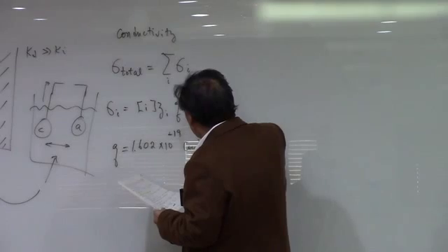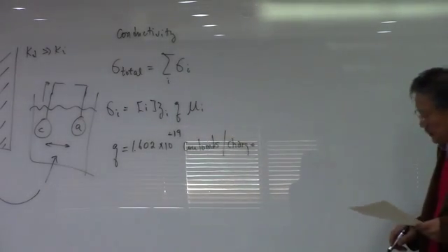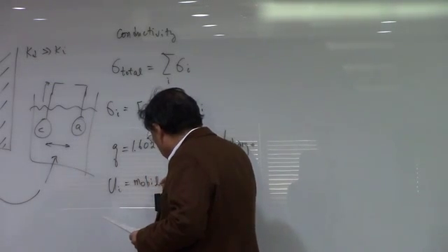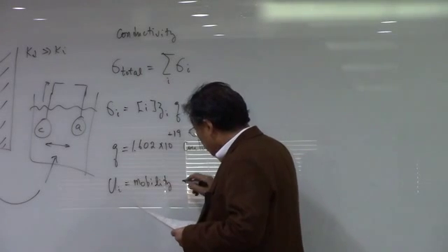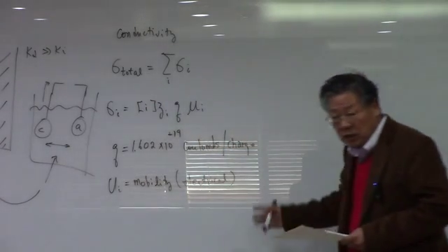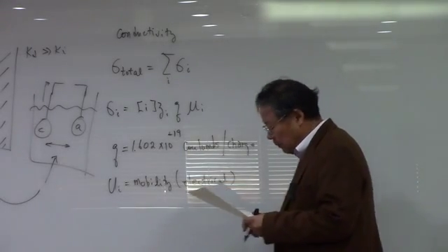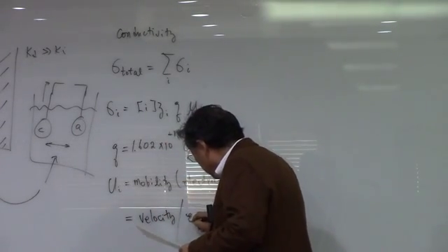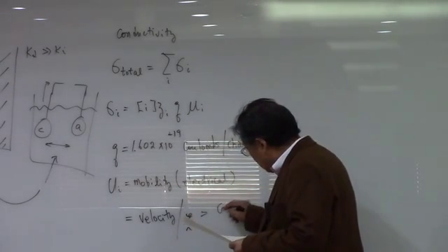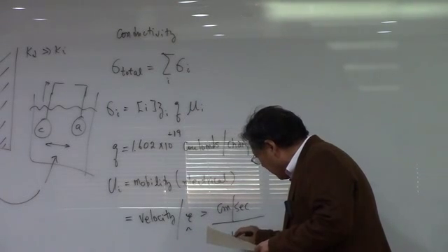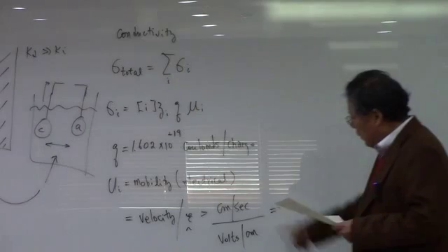And we have to multiply the whole thing with the mobilities. And u_i is the mobility of that species. Well, we should say it's electrical mobility. There are many different kinds of mobility, but in this case, obviously, it is electrical mobility. And that is the velocity divided by electric field. The velocity has a unit of centimeter per second, and the electric field is volts per centimeter. So the mobility has a unit of centimeter squared per volt second.